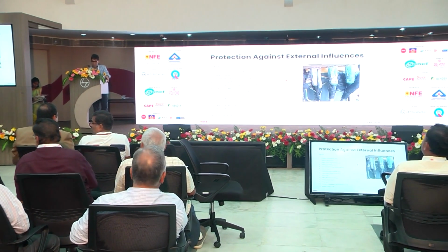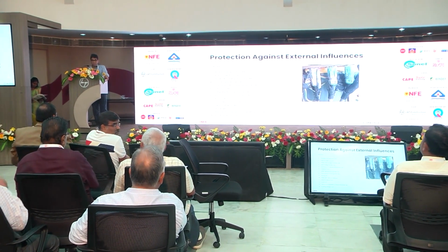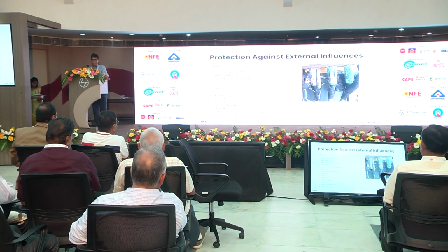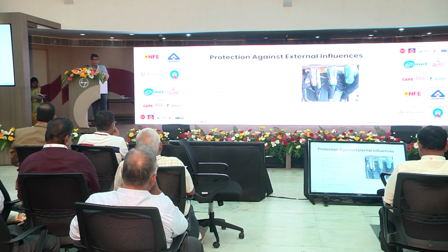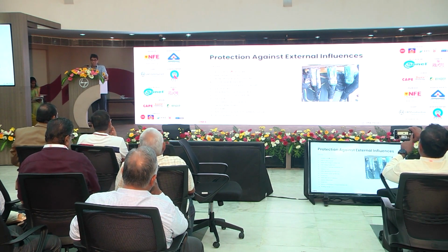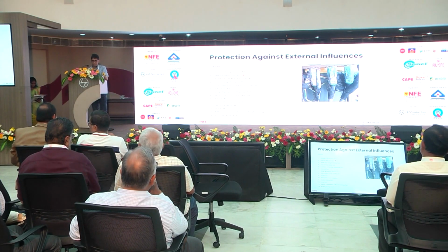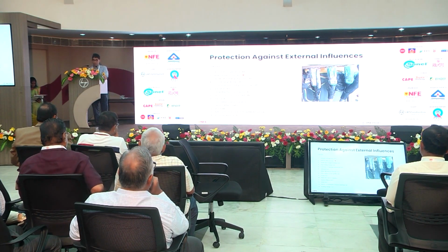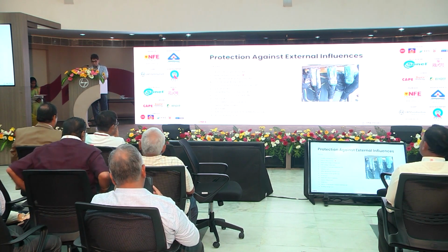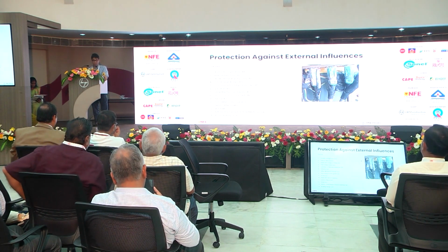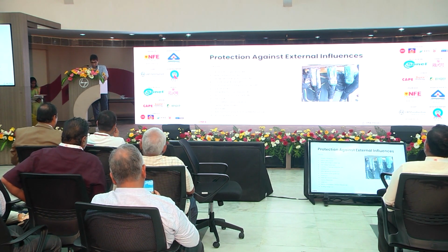So let's look at protection against external influences. You see this gland here? It's a decently installed gland, but it's just not rated for the external influences that are present. So firstly, we've got ambient temperature. Then we've got external heat sources. Water or humidity, it's a big one. Foreign solid bodies, dust, etc. Corrosive or polluting substances, such as even salt in the air.